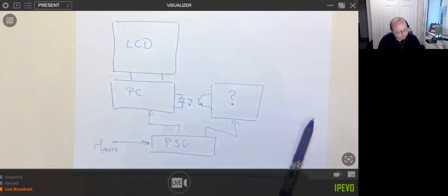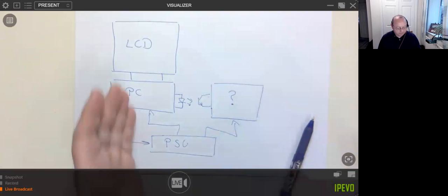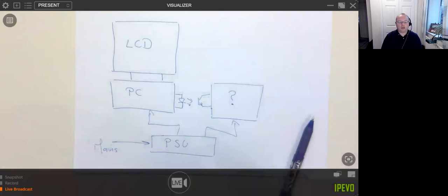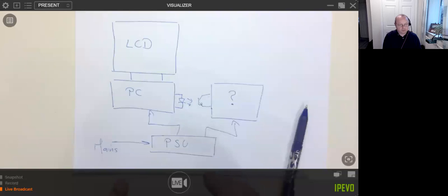So a really neat and simple way to deal with software, where the software might change, or if you've got a bought-in PC like a Raspberry Pi or something where you've got no control over the processor part, is we designed the electronics such that if the software had a hissy fit and tried to do something really crazy to the patient, the electronics would spot that crazy moment and make it safe. And of course, that's all then part of the risk analysis, isn't it?